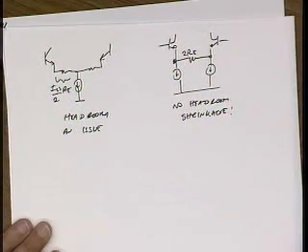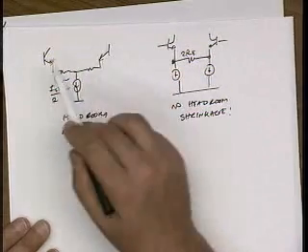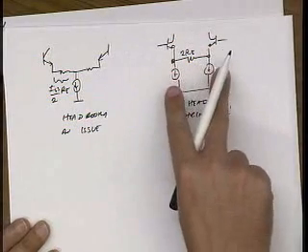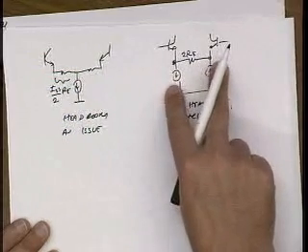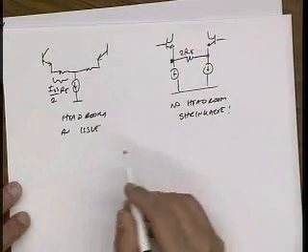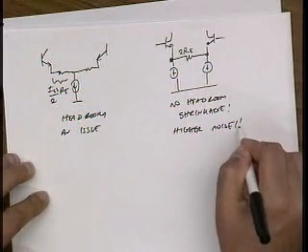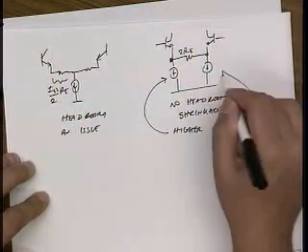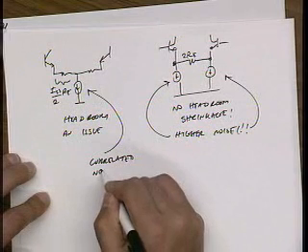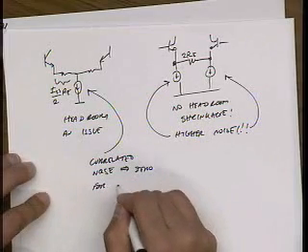Depends. If the output's differential, no, because it's a common mode signal, right? Because I inject the same noise into both sides, and so I subtract it out. Here, these are two different current sources, so even if I take a differential output, the noise sources are uncorrelated. So then I see the noise of the current source. Okay. So this one has higher noise. So this one is basically correlated noise, which is roughly 0 for differential output.